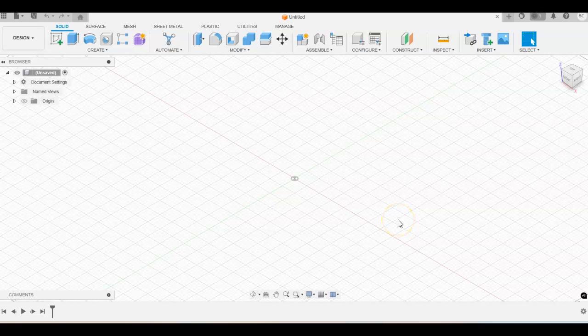Alright, in this tutorial video I'm going to be demonstrating problem 3-7, which is on page 3-53 of your text. As we take a look at this, we can see the dimensions given in the front view, which gives us our overall width, and two other dimensions there on the horizontal plane. And of course we're given a 30-inch dimension up, so we've got this corner cut out, and we have what is really referred to as an oblique angle kind of cutting across the path.